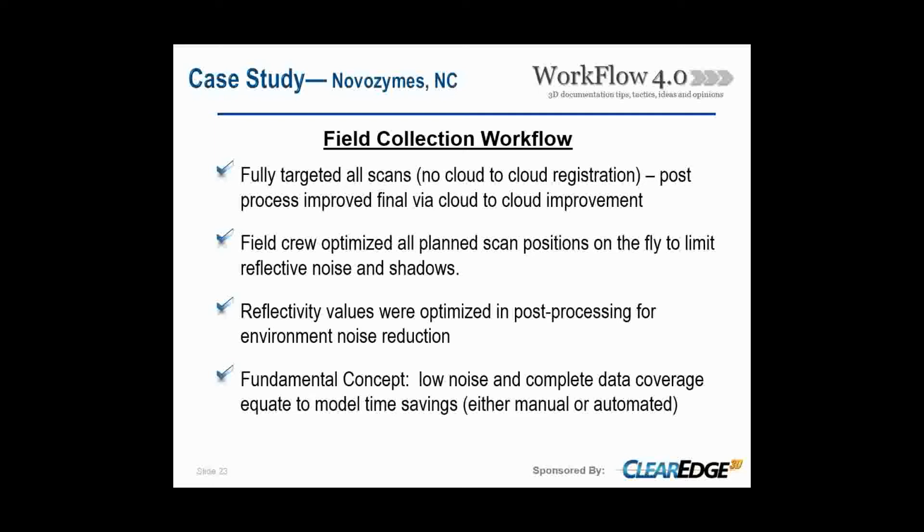So the way we go about it, fully targeted scans with no cloud registration, but we post-process with cloud improvement once we have everything targeted and a fit between the two precision instruments. We plan out all our positions, but then the field crew can optimize them on the fly, and they did a great job to eliminate shadows.